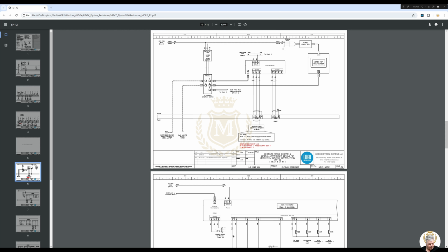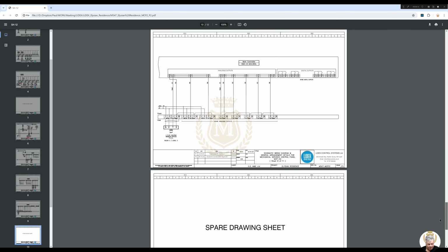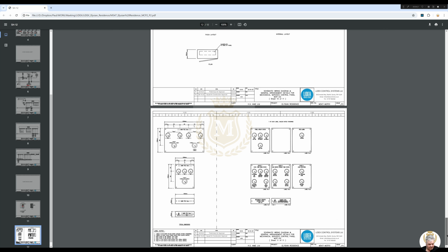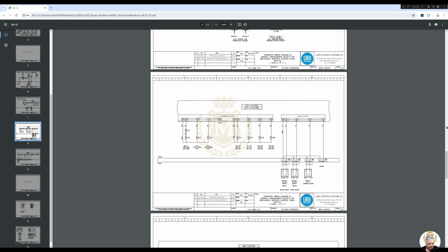I mean, that's saying Modbus RS485 to module 1 on sheet 18, but I believe we don't have a sheet 18, so it's just something left and copied in there from the last drawing.